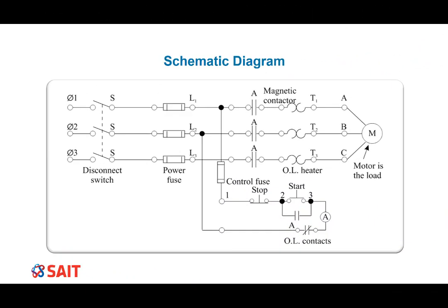The schematic is normally used to design a circuit from a written or verbal description. It shows the order of the components making up the circuit and the operational sequence of the circuit. It does not show the actual physical location of the equipment or actual wire destinations and connection points. Schematics are great for troubleshooting circuits.